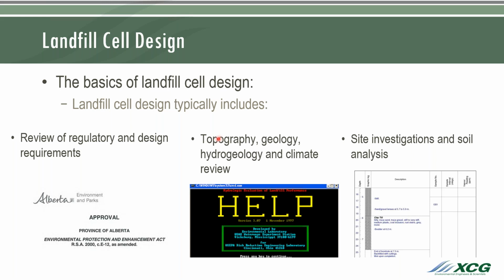when you're putting together your landfill design, be it a specific expansion or if it's a design of an entire landfill. So your topography, geology, hydrogeology, and climate review. I've got a screen grab here of the HELP model, which is a rather archaic program for estimating the hydraulic performance of your landfill and all of its components, but it's still the most relevant tool for estimating your leachate generation rates, how much precipitation is going to make it through your liner, and your cap once it's closed. And site investigations and soil analysis.